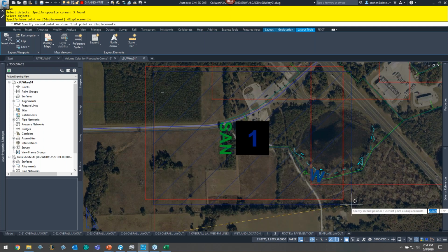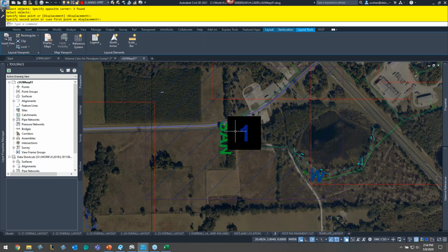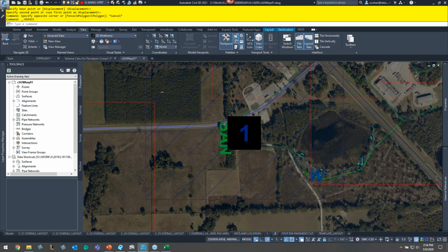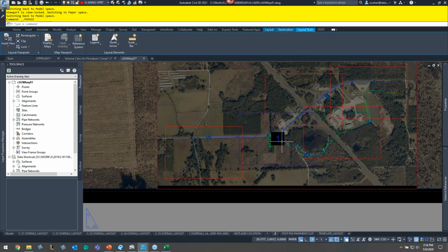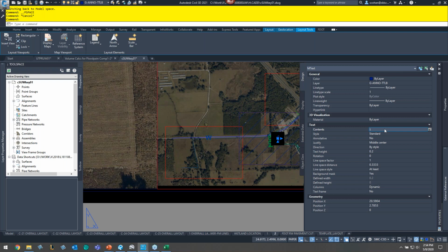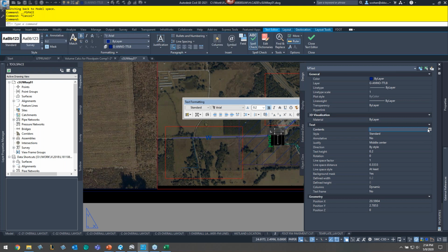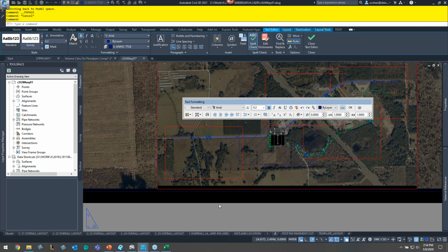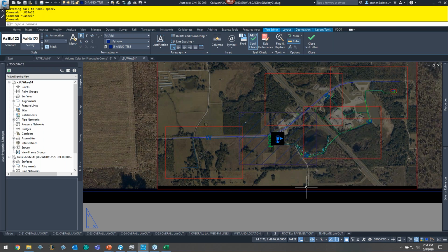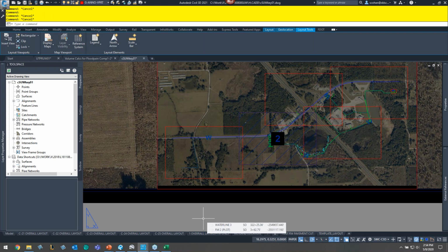And then simply double click, right? Make sure you're actually on the text. Whoops, I'm in the viewport now, I think. If I remember correctly, let's see. Yeah, right. And then just obviously just change this to, come on. You get the idea. I'm not going to bother but you would just change it to number 2, right? You can do it here. I could also select this here and just change this to 2. That's another way to do it as well. You can just click here or click edit. That works as well, right? And then 2. And we're done, right? How easy was that? Again, the named views just save you a tremendous amount of time, okay?